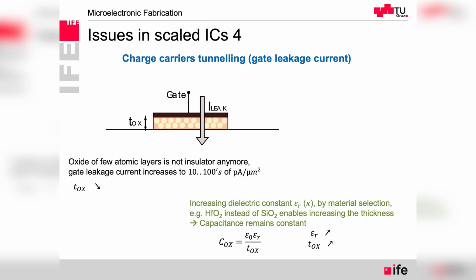So there is the tunneling leakage current, and when I was looking on the progress of some technology nodes, I could see that at some point it was as much as 10 to hundreds of picoamps per micrometer. It was not the peak because also it was different for p-channel, n-channel transistors, and at some point it was really disturbing for making a good design, and not only for analog design, but for digital chips, the big chips, the power consumption was enormous.